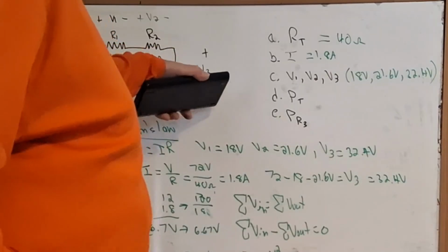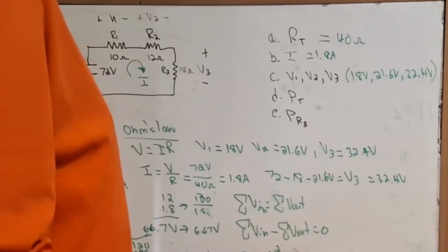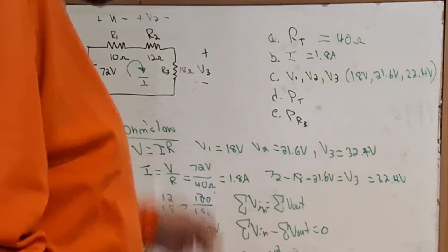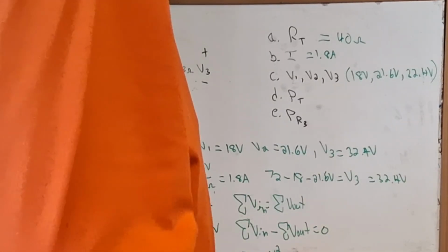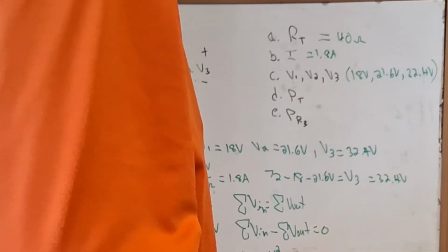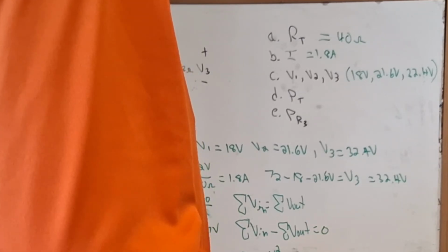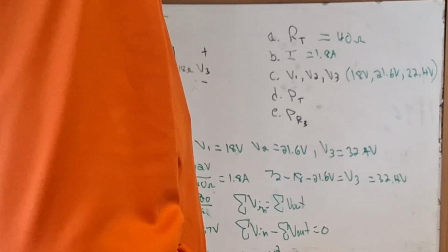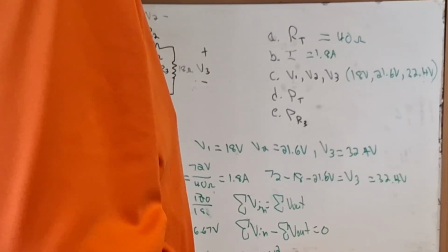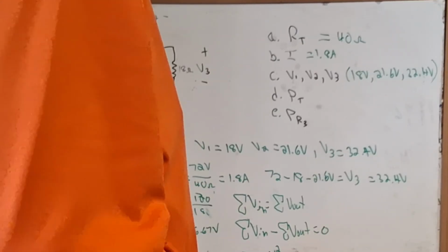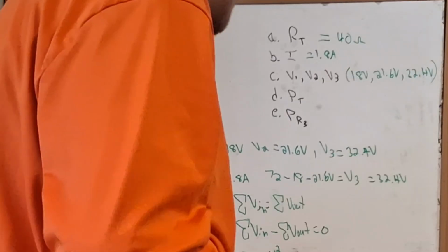What about right here? Well, I could just use the ohms resistance. Let's take the total current, 1.8 amps times 18 squared. Oh no, I squared. It's I squared times R. I squared, 1.8 amps squared times 18. That's going to be 58.32.